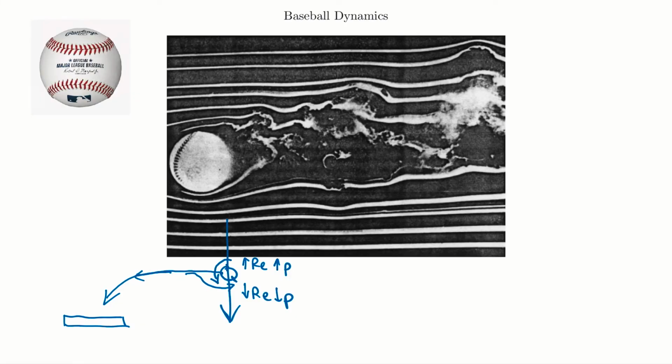And we see in this picture here that I've shown, we have a smoke photograph of the flow around a spinning baseball. So the flow is from left to right, right? So this way, the ball is spinning counterclockwise, as in the example that I showed below. So that'd be like a curveball, we can think of it if we're looking at the side of the ball. And we see how earlier separation here, delayed separation here, right? So our wake moves upwards, right? And that accounts for this downward force that we're seeing, and the crowding of the streamlines too at our lower pressure we can observe.